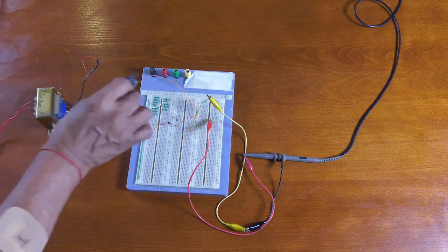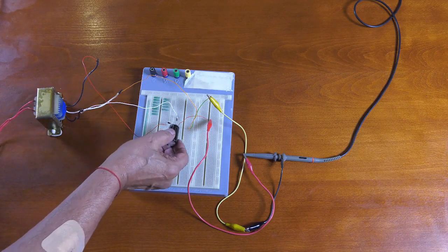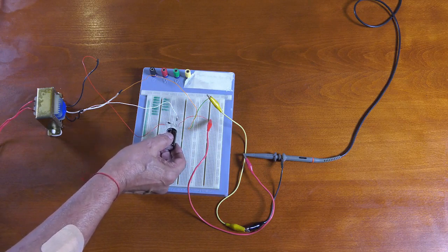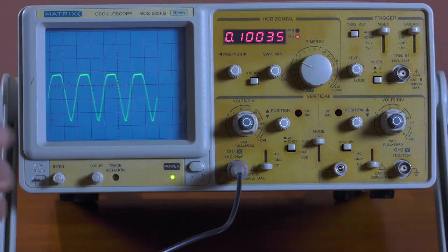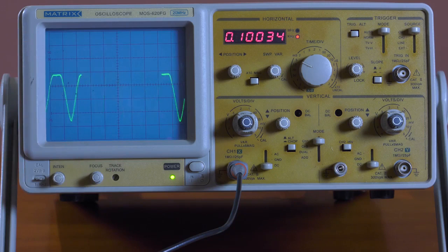We are still with a full wave bridge rectifier circuit with 2 diodes. But as you can see on the display on the oscilloscope, we still have a pulsating DC. We need to, as we've discussed, remove these peaks, which we call a pulsating DC. And we do that quite simply by adding a capacitor. Notice the waveform changing to a straight line. That's what we are aiming for the moment you add a capacitor.